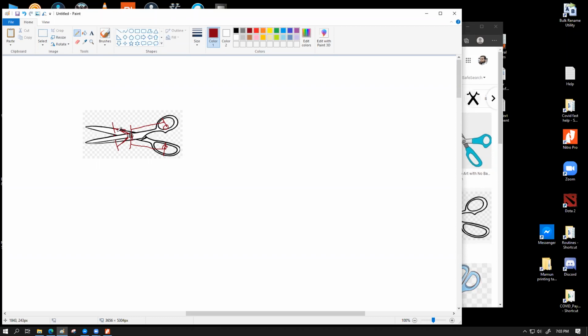Or in other terms, it is much easier to cut objects with a scissor the closer you put it to the screw or the nut in this case, which is working as the pivot for these two arms of the scissor. So if you press on the far end, you have to press pretty hard. You cannot experience it much if your scissor is quite sharp, but when the scissor becomes dull, you can actually experience it. For a dull scissor, it is easier to cut objects when you place it close to the bolt over here, not on the end. That can prove to be quite difficult for not so sharp scissors.